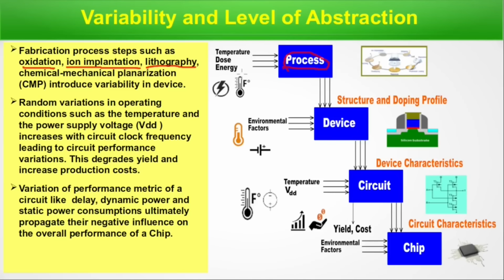The first batch of n wafers has ion implantation done with some dose and energy specification, and for the next batch of n wafers, this ion implantation has been done with dose or energy slightly different from the previous run. So with this ion implantation, how much these ions penetrate and where it would have the highest concentration,